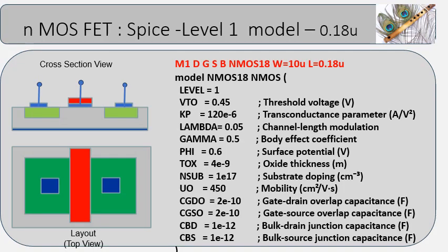A transistor SPICE model is a virtual device presented in mathematical form. It exhibits the device electrical characteristics, taking into account the device parameters like material characteristics, process parameters, geometry and the device parasitic. A FET model is a mathematical representation of the device electrical behavior under various operating conditions and is used in circuit functional simulation. Model enables designer to simulate the circuit performance even before prototype fabrication.